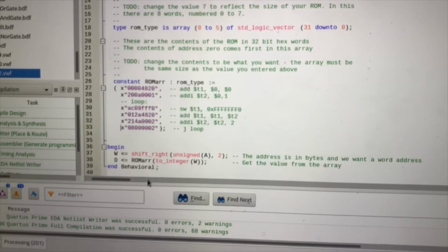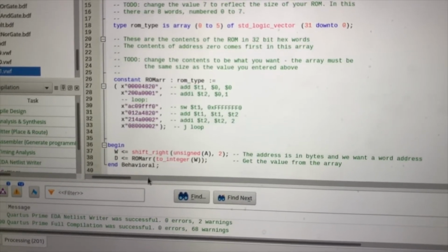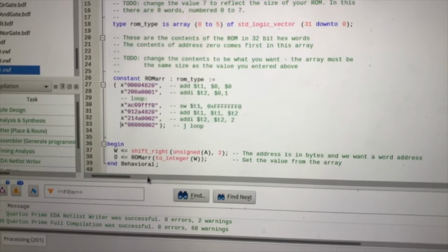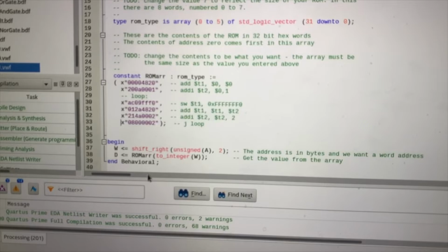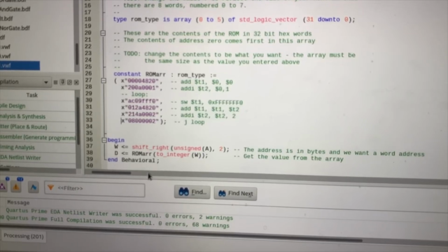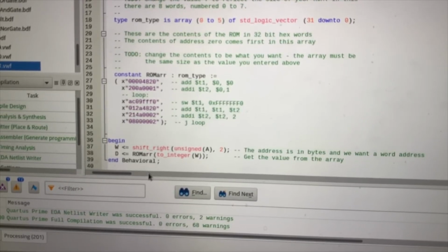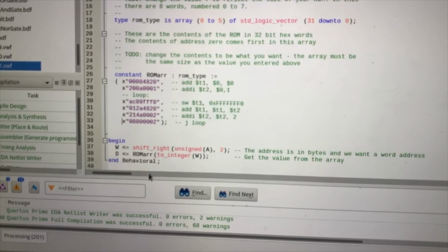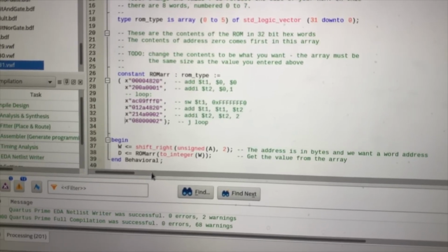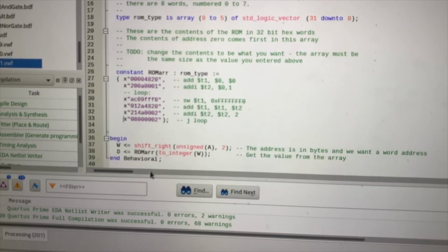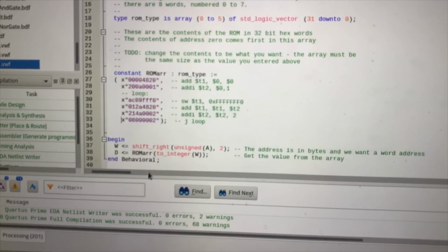Next, we add st2 to st1 and store it as the new value for st1. Then we use addi to add 2 to st2, which gives 3 for st2, and we have a j loop which loops back and displays 4 on the FPGA. This keeps looping to display further values such as 9, 10 which is 16 in hex, and 19 which is 25 in hex, etc.